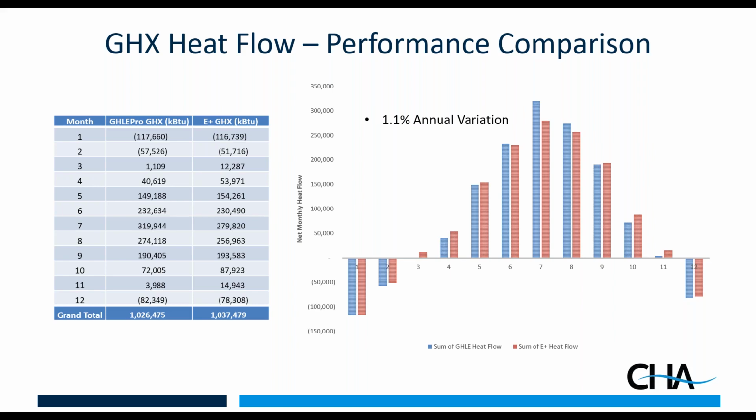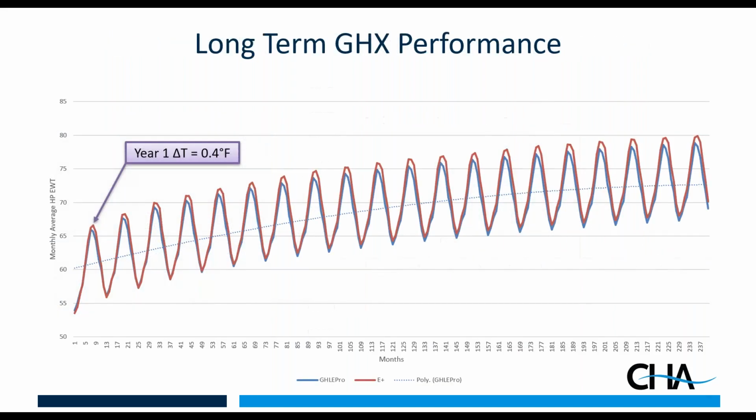So we want to take that one step further, because now in more recent versions, EnergyPlus can simulate buildings over a longer time frame. So we said, okay, well, let's take that. We're going to simplify the data we're saving. So instead of an hourly saving of data, we're going to do it on a monthly basis, so we can run it out further and not create giant output files.